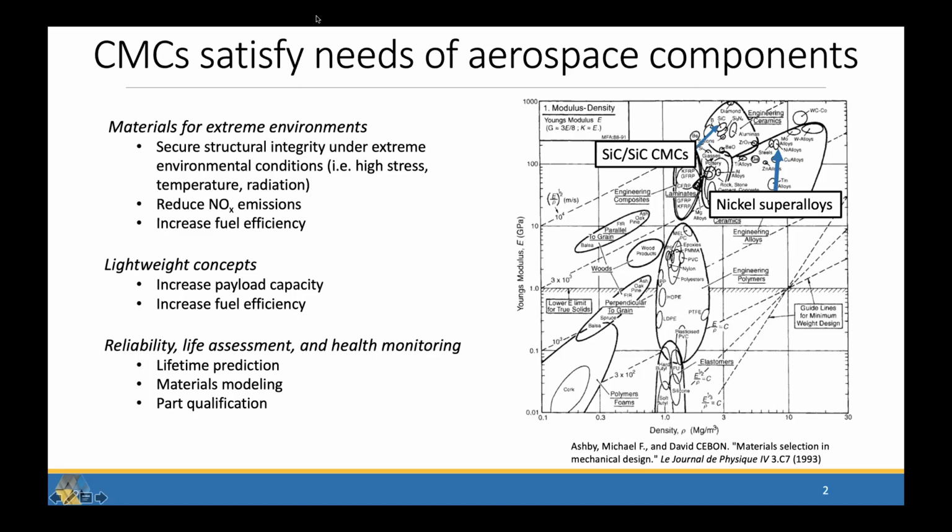There's been a lot of work on using acoustic emission to look at bulk damage, but it can only identify where the damage is and its propagation. You can backtrack where it was, but you don't know what it was. And in order to structurally health monitor these composites, a matrix crack is a lot different than a fiber break. And if you start seeing a lot of fiber breaks, that means you're nearing some sort of catastrophic failure. So it'd be incredibly useful to be able to know what damage mechanism was causing that signal.